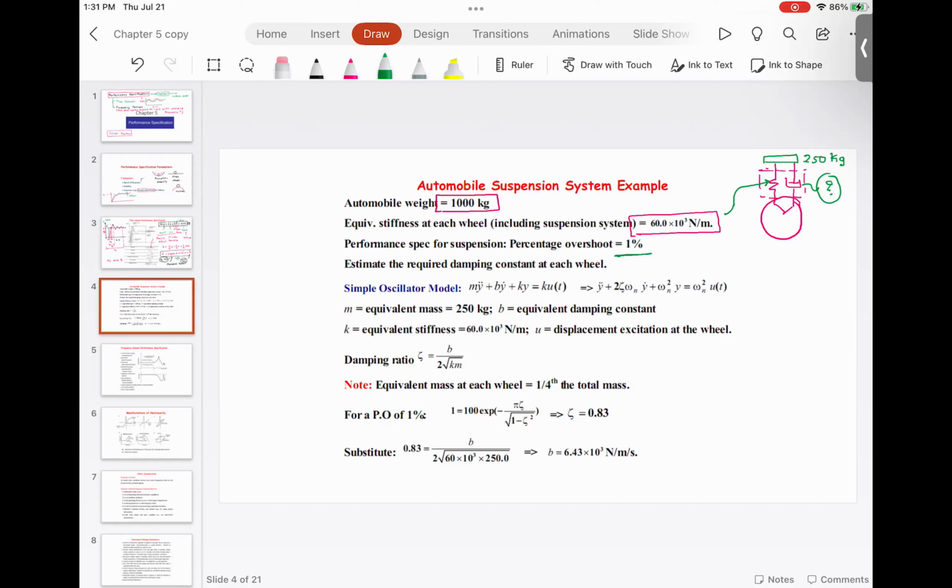So the Mercedes suspension designers have specified that whenever somebody puts the vehicle into sports mode, the percentage overshoot is very low, say 0.5%. If somebody puts the vehicle in comfort mode, then you can have a little more overshoot, but the oscillations should decay over a period of time. It means you should have a smooth ride. So you can tune these parameters.